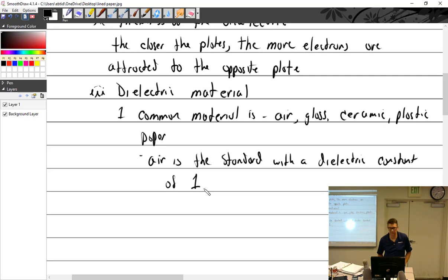So is that to say that these plates are wrapped up in such a way that they don't touch each other? Yes, if they touch each other, they short out. One of the problems with capacitors is that that's exactly what happens. The dielectric material, in this case tissue paper, will break down. If you get enough voltage through here, it's going to arc through the paper, and when you create an arc spot and weld two pieces of plates together, you have a short at that spot, and you start to lose your capacitance.